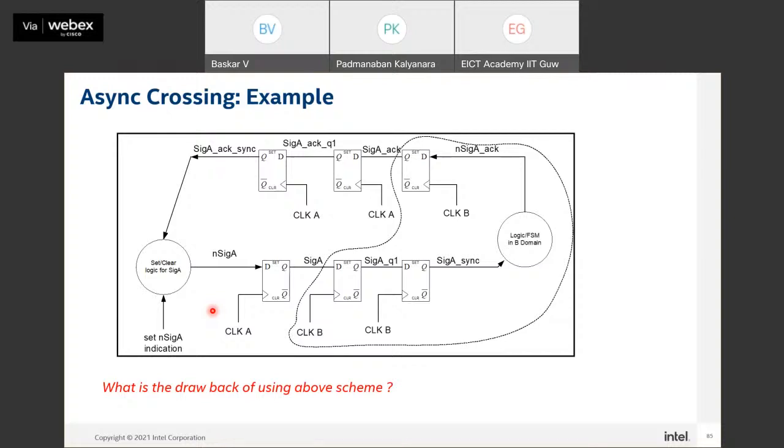If you are building a design, the unique selling point is how many operations you can do in a given clock period, or how fast you are processing the data and throwing the output to the outside world. In that context, if my design is going to take n number of clock cycles as latency, then this design does not have any unique selling point. So this is the biggest drawback, the latency.